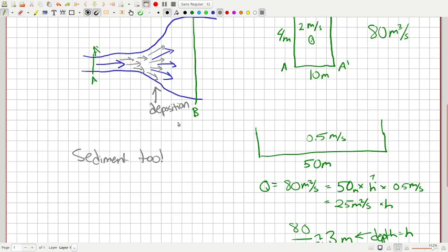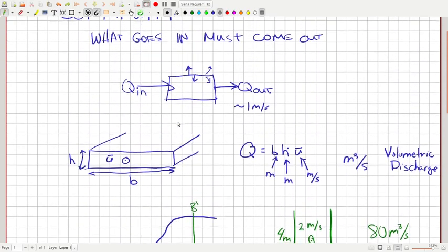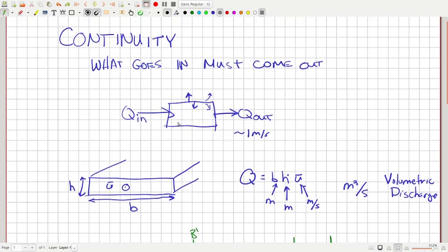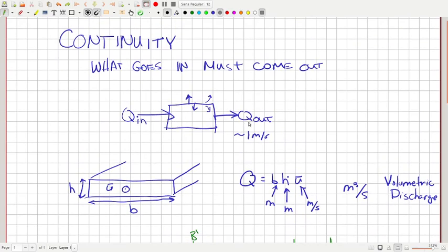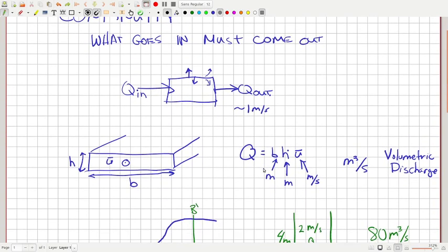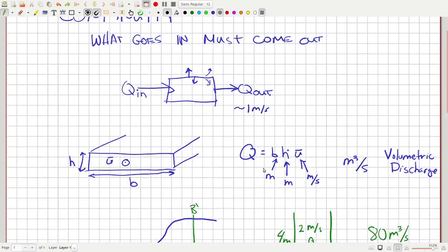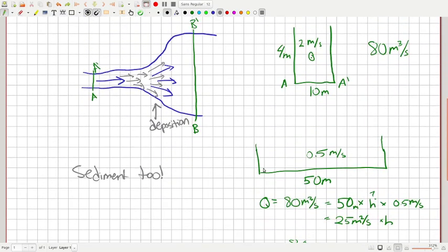To summarize and make sure that we back this all up, get back to the beginning. If we have about the same amount of stuff coming in as going out, then we have continuity. What that means is that if we're looking at discharge, we can use continuity to say that the same discharge must be going through different cross-sections, and therefore we can use it to solve for unknown values when trying to think about how much water is going through one chunk of a river, or one cross-section of a river, to use the formal term, versus another.